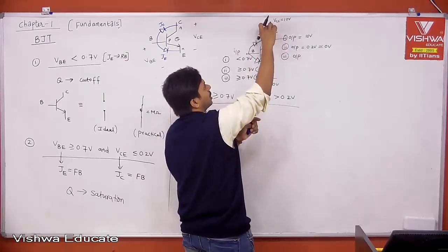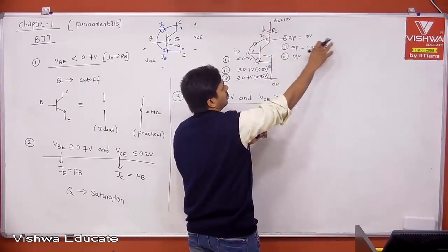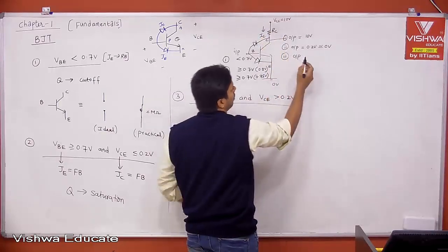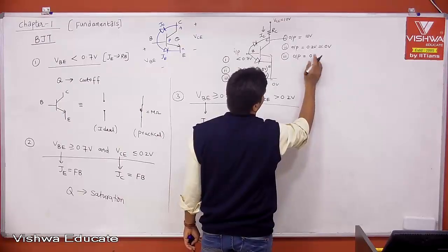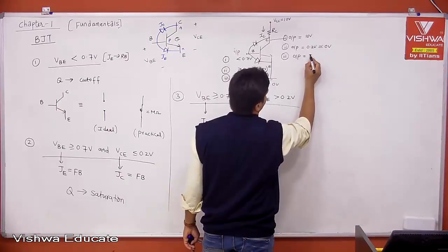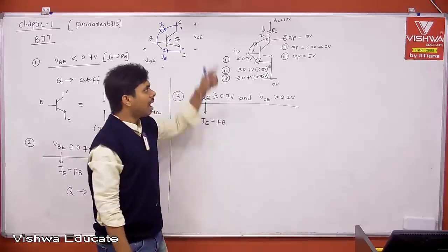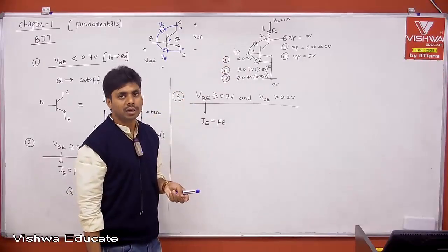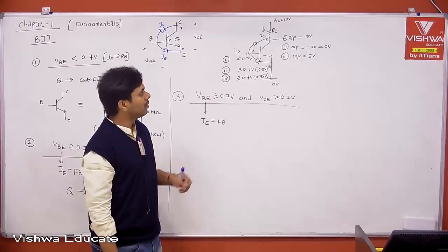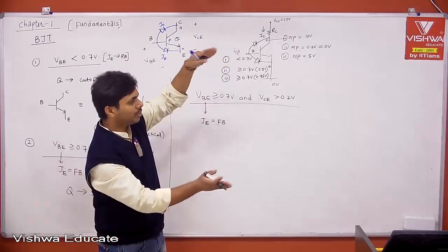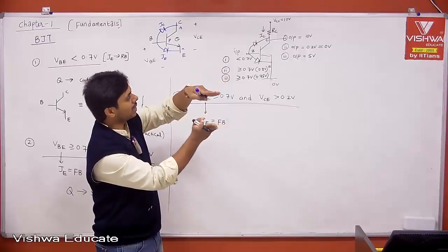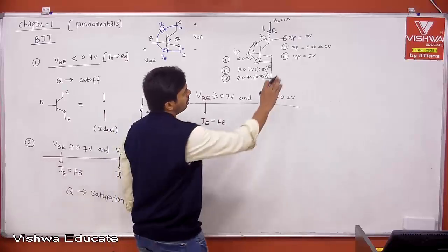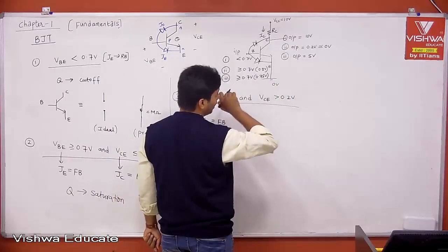Earlier, the entire voltage we had seen here, therefore only 0.2 or 0 we had seen here. But now it is only 5 volt, which is intermediate, and this is 5 volt. Therefore, let us say it is around 5 volt, like the midpoint of rail to rail. Typically, that is what people try to do to keep the transistor in active region. Therefore, whenever you get a swing about it, it will be 10 to 0 if the output DC voltage is exactly at 5 volt. The DC voltage is biased in the transistor to keep it in active region.